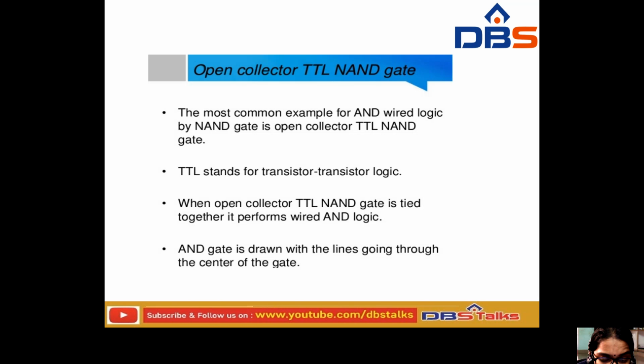Here you have to take the approach of TTL, that is transistor-transistor logic. By using transistor logic itself, we are going to perform the task. Here the most common example of wired logic by the NAND gate is the open collector itself. And when an open collector TTL is a TTL NAND gate, it should be used as wired logic.